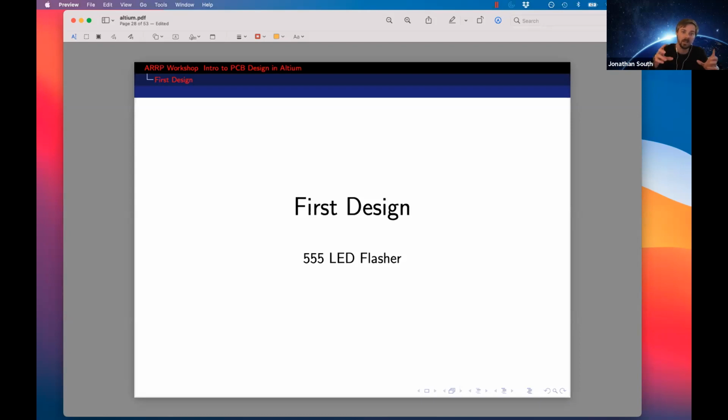So if we're doing mounting holes or vias or through holes, exactly how those holes are made and how they're laid out are defined in the NC drill file, which I guess needs to be separate from the Gerber file. I'm not super sure of exactly the layout of that. All I know is that, at least for PCBWay, you need to get the Gerber files and an NC drill file.